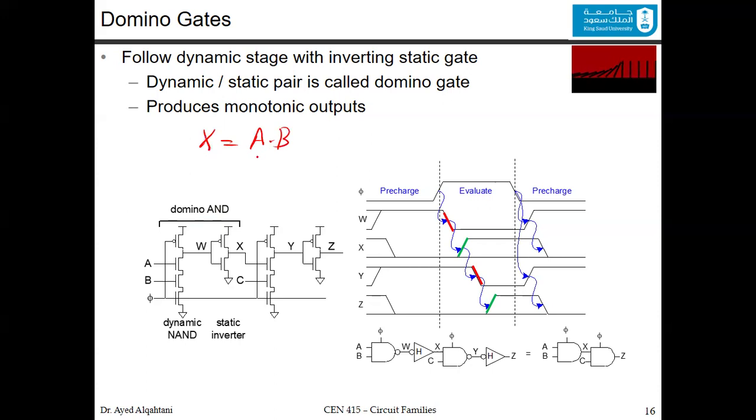So it's simple, an AND circuit. In the domino, what you do is you draw the dynamic NAND, or the dynamic circuit. Let's say we don't know what to do here, so you draw a dynamic circuit and nothing here. You can choose to have it footed or not footed, followed by an inverter. Since there is an inverter all the time, you don't need the bar anymore that we are requiring in all the designs. If you have a bar, you need to get rid of it. So now this circuit here is exactly the one that you design over here.